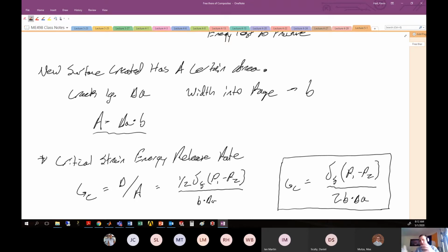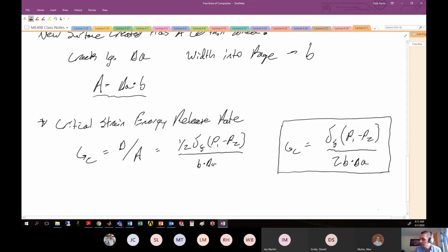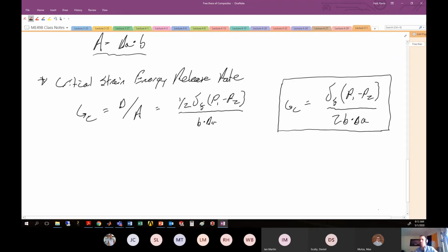Okay, so you go, go, go until you've run out of material and it fractures all the way through. All right, so practically speaking, it would be more useful if we had some experiment where it was like load a little bit, then fail, load a little bit, then fail, and so forth. Okay, so that is a specific type of brittle fracture known as stick slip fracture, which is what we're going to talk about now.